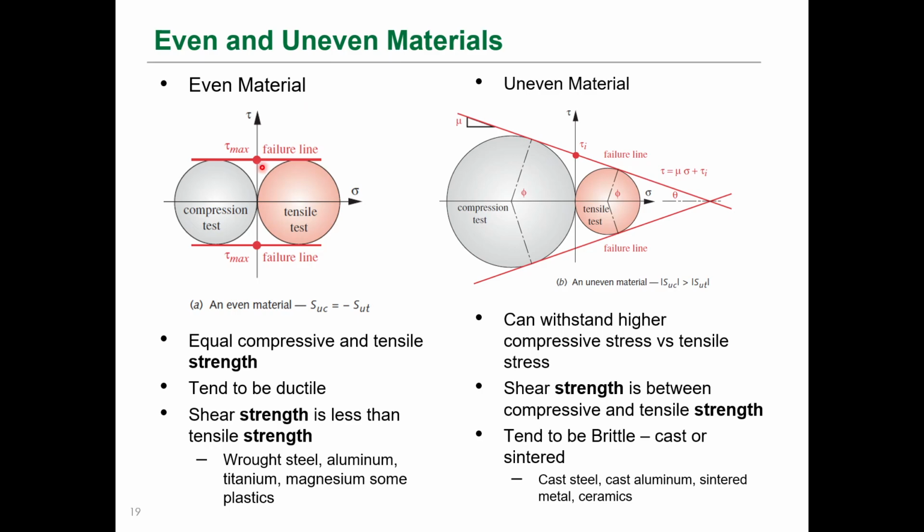And if you go to a certain principal stress here and get failure, usually it's going to fail actually here at this max shear. So this is your failure line. Over here, these define your failure envelopes.